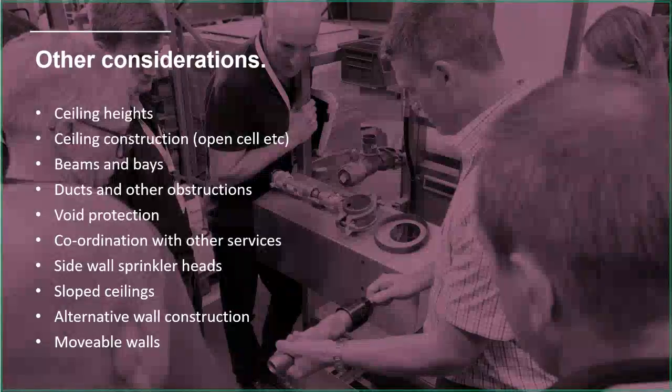If you've got a screen that could be pulled across to divide one room into two, like conference centres, schools, etc., they're going to have the ability to have a wall which is there one minute and gone the next. That's a challenge for a sprinkler designer, because we need to make the sprinklers work in both scenarios. We need a compliant design when the wall is there, and we need a compliant design when the wall isn't there. It can lead to some interesting challenges.